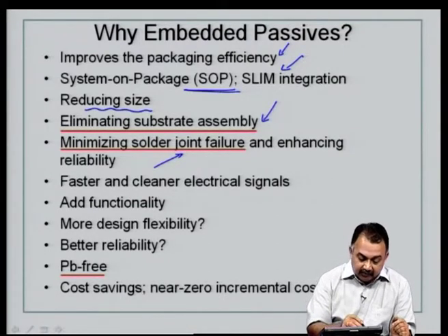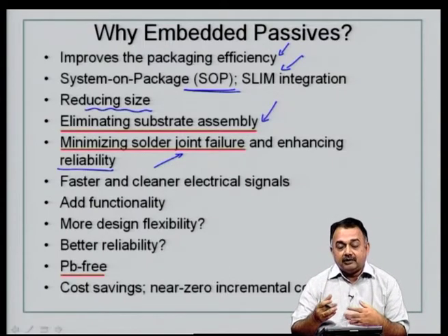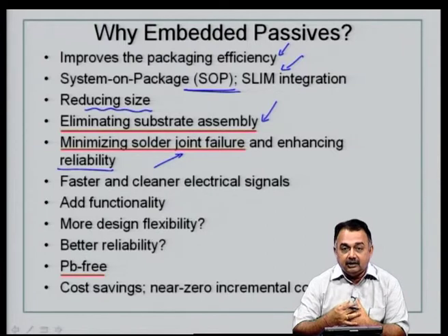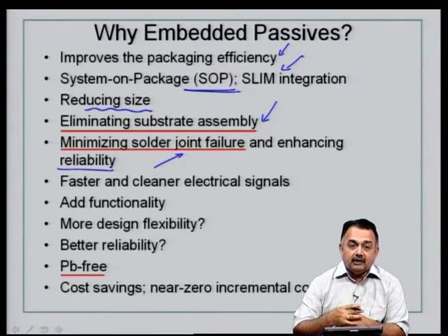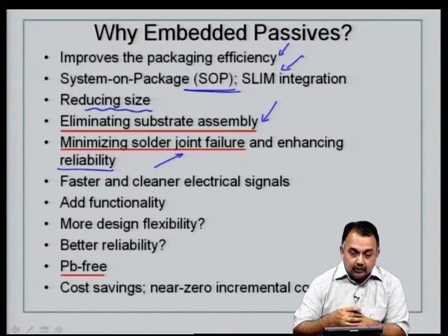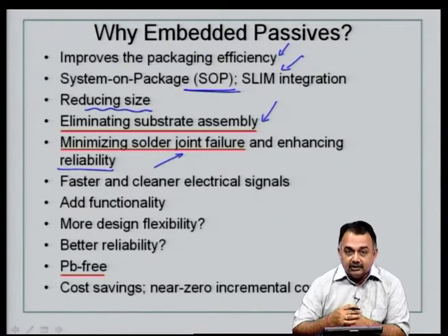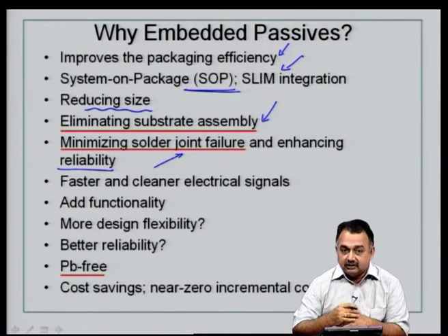Therefore, the reliability is built onto the printed wiring board, and obviously, once the printed wiring board with these devices is built, you are going to check the reliability of that system, you are going to check for failures. You would be doing a bare board testing with the passives on board. You would also be doing thermal humidity cycling with the passives on the board, and therefore, you could get a good measure of the reliability issues connected with such a system.